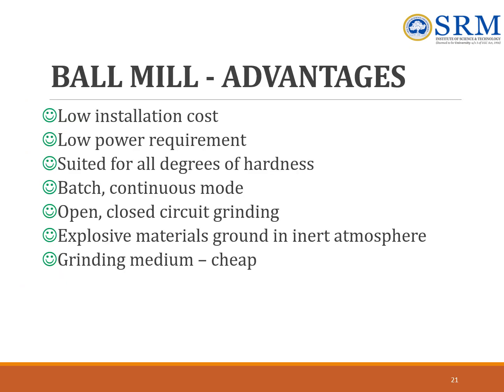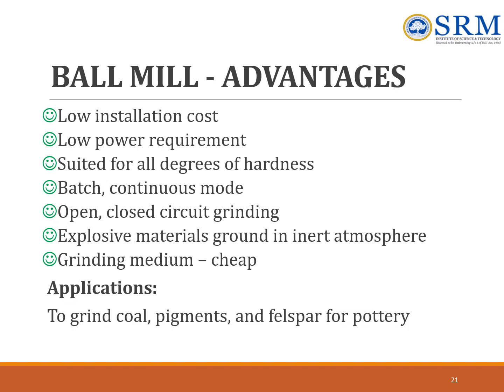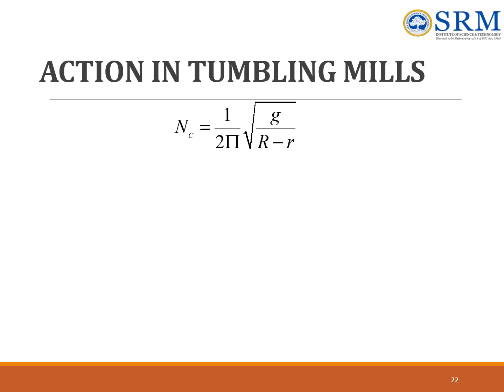Coming to the advantages of ball mill: it has low installation cost, low power requirement. It can be suited for any degree of hardness. It can be operated in batch and continuous mode. It can have closed and open circuit grinding. Even explosive materials can be operated in an inert atmosphere in a batch mode, and the grinding medium is cheap. Application: it finds application in coal, pigments, feldspar for potteries.